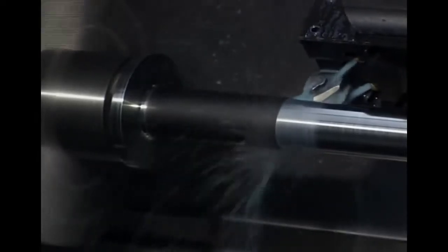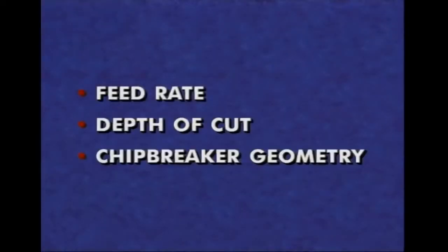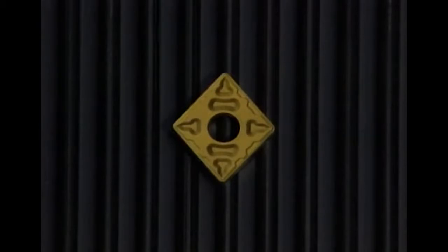In turning, effectively breaking a chip is just as important as making the chip. A properly breaking chip contributes to an efficient process and a good finish on the workpiece. Badly controlled chips are a nuisance, a production bottleneck, and are potentially unsafe. Proper chip breaking results from a balance between the feed rate, depth of cut, and the chip breaker geometry in the cutting tool. The chip breaker groove is molded into the insert in a wide variety of proprietary designs.